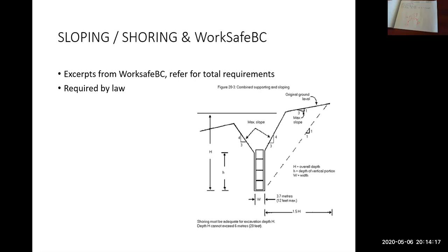Sand would be less than that. Silt and clay would be less than that. Probably in the 2,000 kilogram per cubic meter range, somewhere in there for silt and clay. Sand is probably maybe 1,800 kilograms, so 1.8 tons per cubic meter. Those are good rules of thumb anyway. Does that answer your question, Bruno?